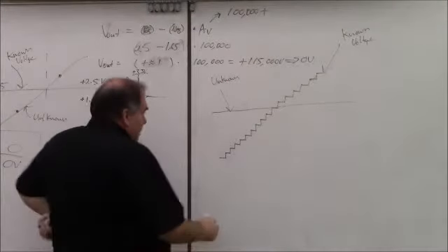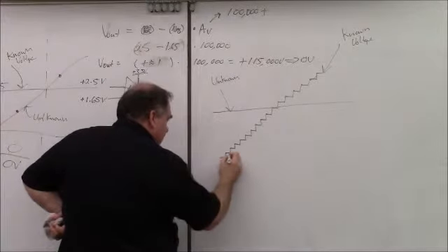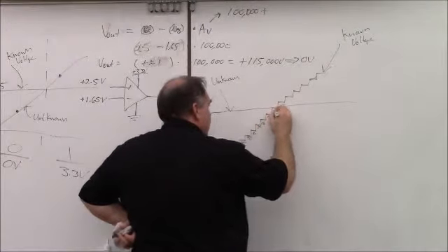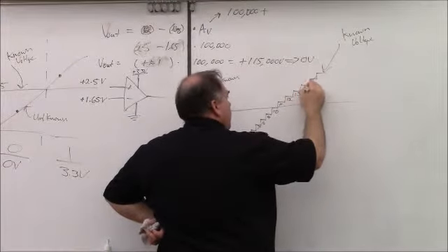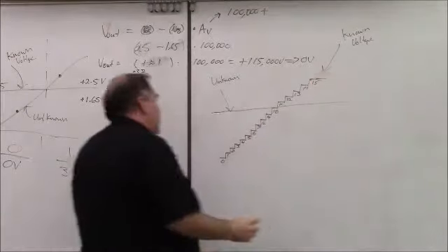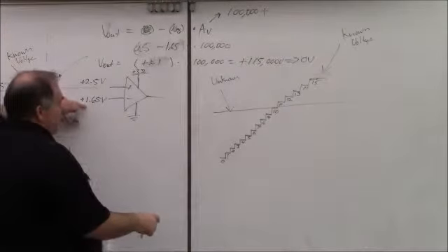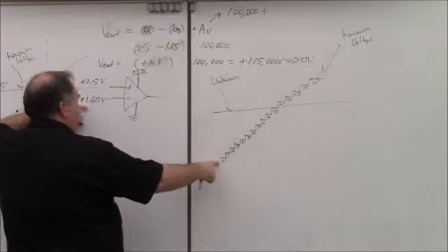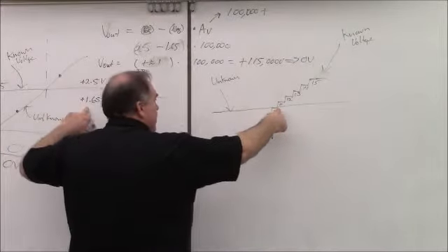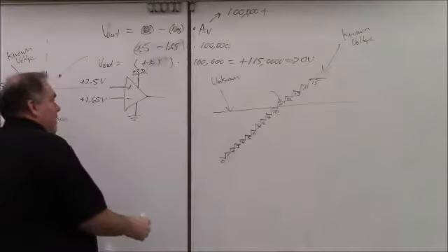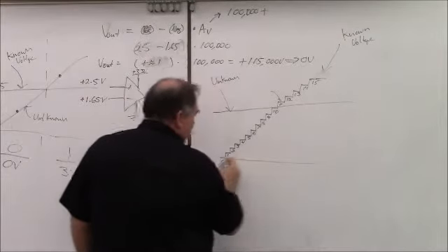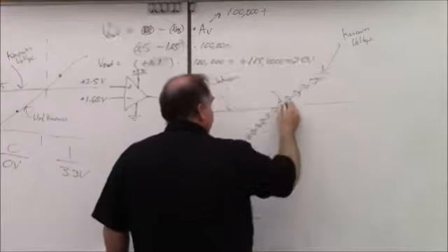And if we keep track of these steps, and we call this step 0, and this step 1, step 2, step 3, step 4, and so on. We'll just go to 15, a nice stopping point. Right? Then what we could do is we set our known voltage, and then we look at the output of our comparator. Are we low or high? And we do it again, right? And we continue up this stair step until we get to 11, and at the point when this voltage went above this voltage, the output of the comparator went from 0 volts to plus 3.3 volts.